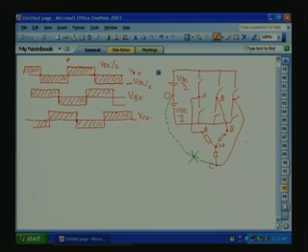Now, we know that we have also derived our VAN, VBN, VCN equations. VA0 is equal to VAN plus VNO, and VB0 is equal to VBN plus VNO.